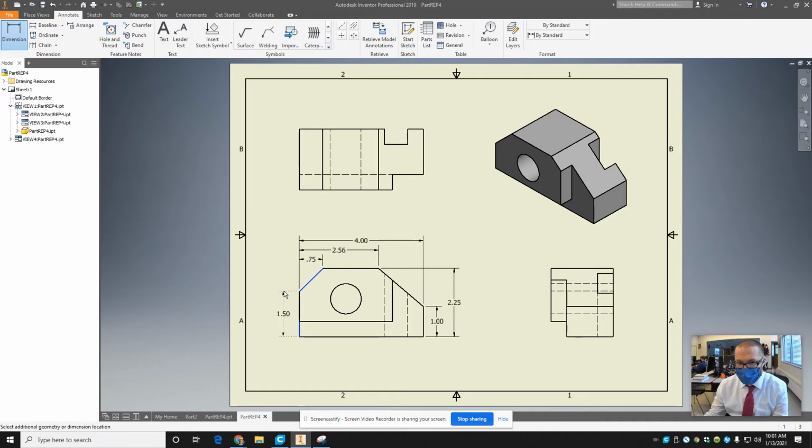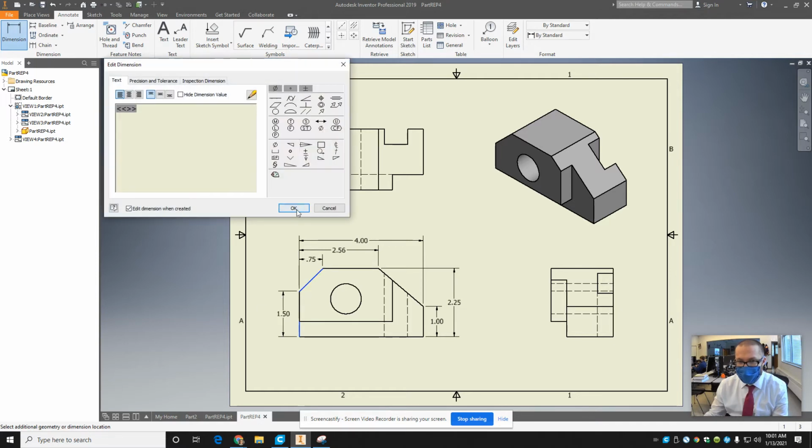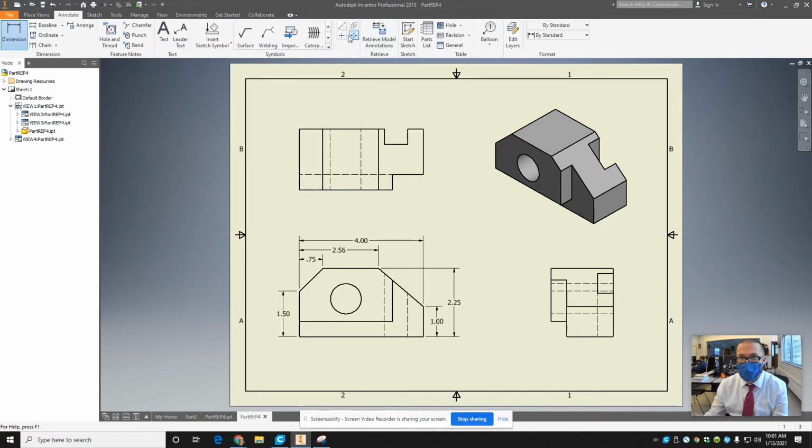Now, all right, one last thing we should do here before we go any farther is put our center mark on that hole. The center line bisectors in this view remind us where the hole is, and this view. It's a little bit hard to see here, right? Because this hidden line is the back of the model, this line. So that kind of complicates things, but also it reminds me, okay, that's the hole. These two lines are the hole.